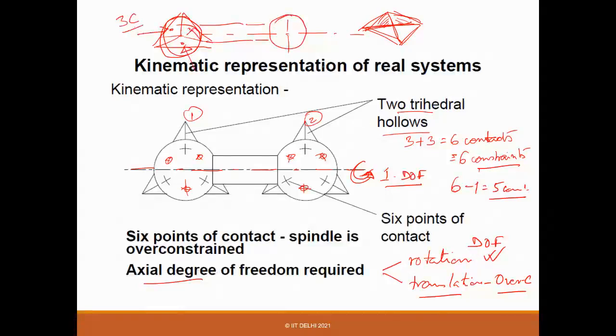I need two constraints so that it can only spin. This is the desired DOF. So it should not go like this, right? At this point, it should not move along this line, right? So 3 plus 4, and of course, it cannot go out of the plane. So for two contacts, I need two contacts, 2C here, right? 2C is a ball in a groove, V groove. It can give me those constraints, right?